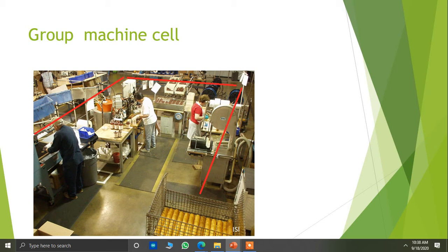Okay, see, packing is one process. It's not just the other thing. See here, it's a sequential process. Can you observe? If the primary person wearing the blue shirt doesn't make the dough, the next process of cutting down, spreading, etc. will not happen, and at the same time, the third process of baking would not happen. In group machine cell, since it is very sequential in nature, the biggest drawback is process initiation should happen at a very instantaneous time, else the whole sequence will be lost.